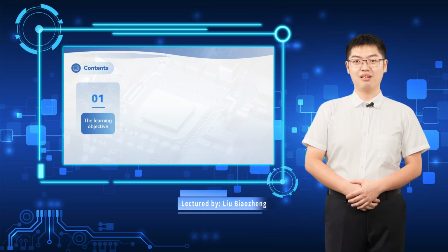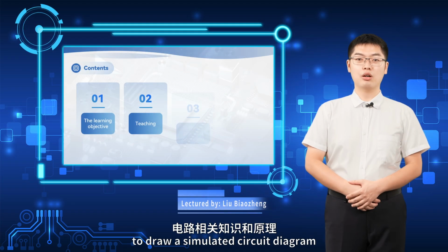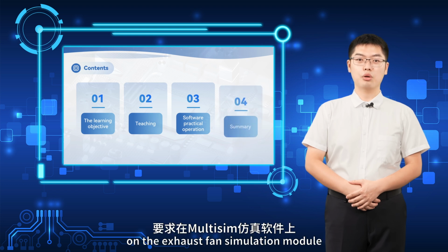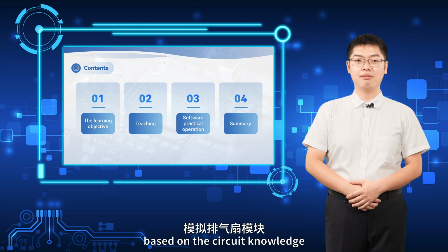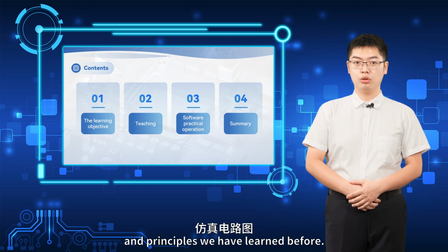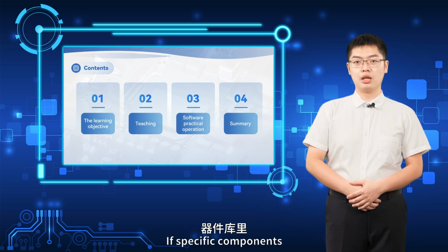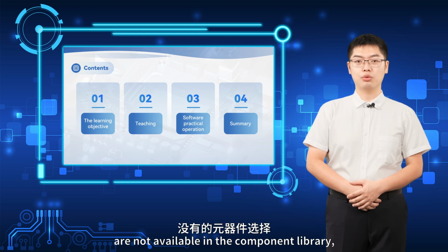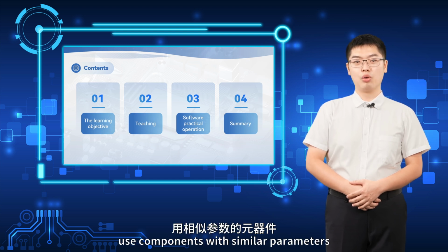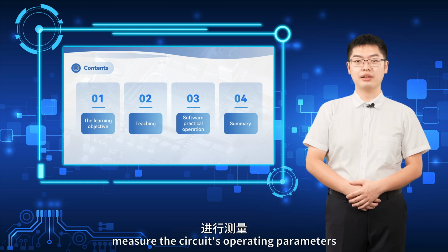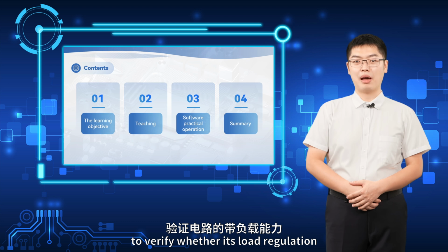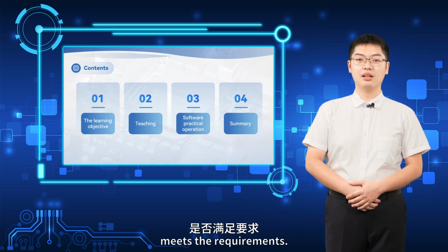Hello, everyone. Now, we are required to draw a simulated circuit diagram on the exhaust fan simulation module using the simulation software Multisim based on the circuit knowledge and principles we have learned before. If specific components are not available in the component library, use components with similar parameters as substitutes. Additionally, measure the circuit's operating parameters to verify whether its load regulation meets the requirements.